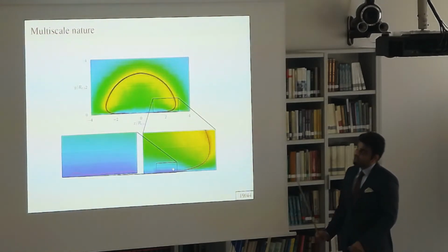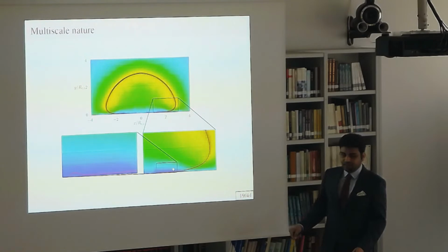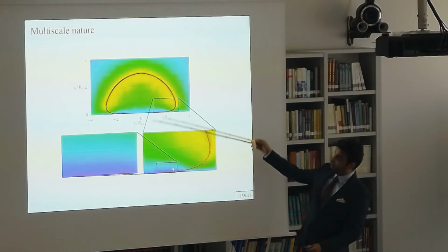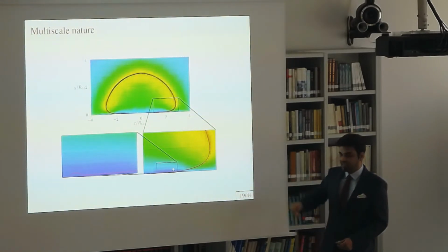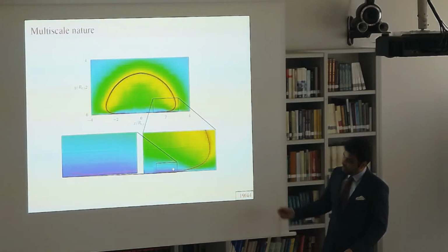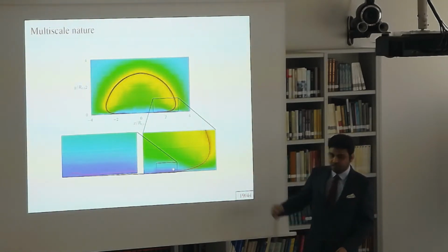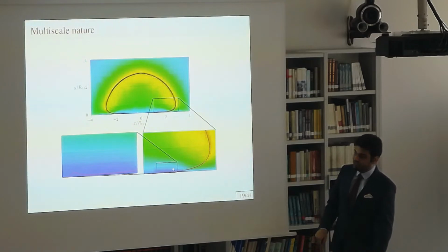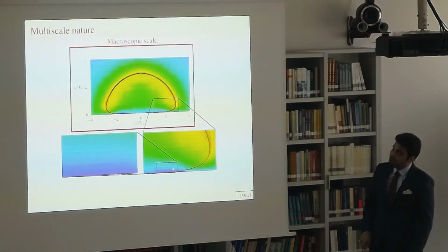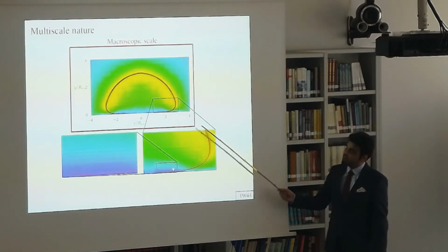Another comment about microlayer formation is that it's truly a multi-scale problem, where one can imagine that at large scale the inertial effects are more important, and close to the bubble the important effects are visco-capillary effects. We start by first describing the dynamics at large scale.